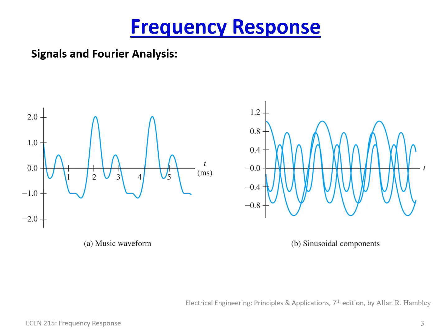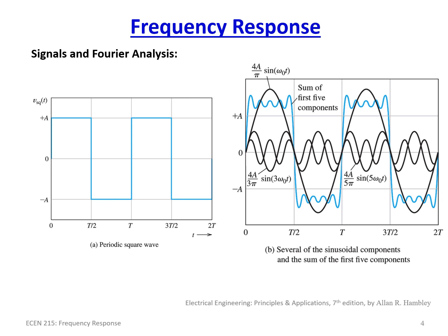To continue on with this concept, we have a digital waveform here. As you can see, this would be an ideal square wave digital, and we're going to be covering digital in a later topic. But if we have a digital waveform where we have 0 volts going to some positive amplitude A in this case, but it could be, say, 5 volts, and then we have minus 5 volts here, there's effectively two states, either +5 or -5, or plus A and minus A. And it's just going back and forth at some period T. So we have this frequency here where we're constantly going back and forth as a square wave.